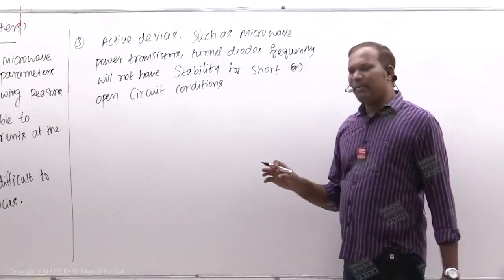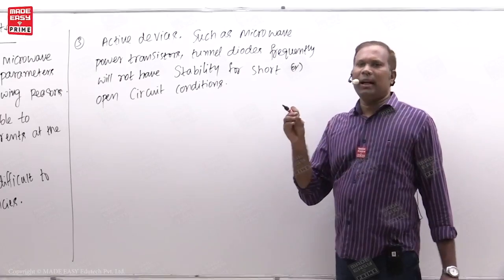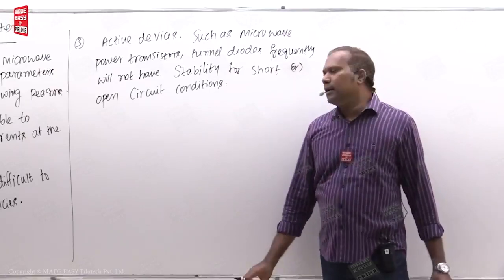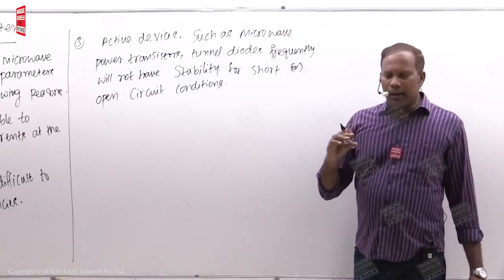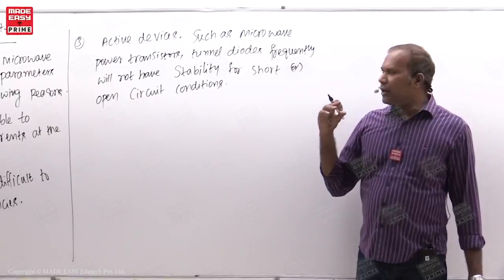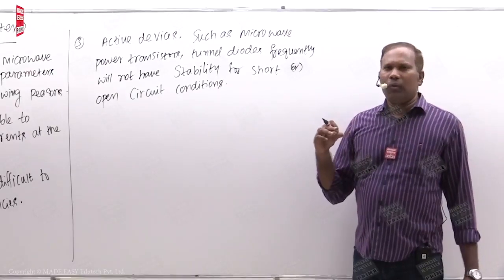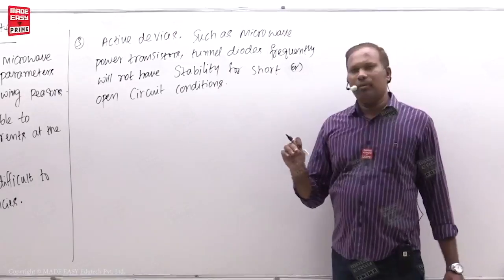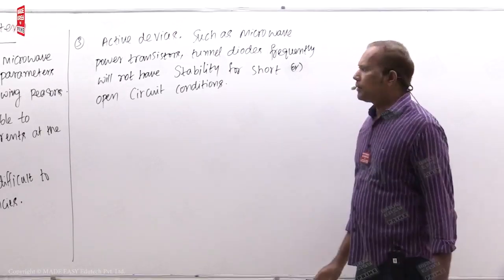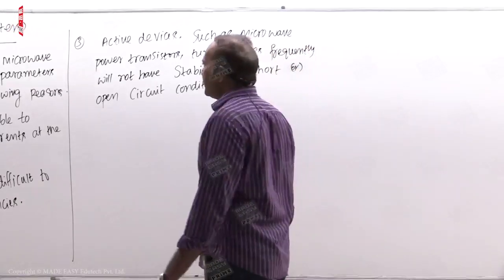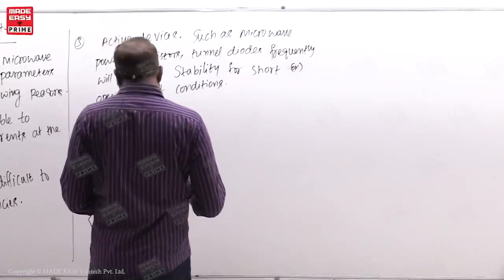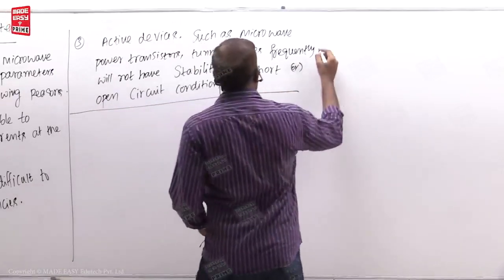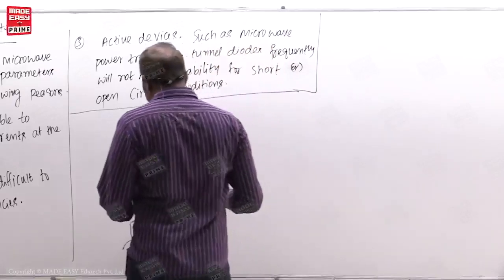Even though you use impedance matching, small reflections will be there. But even small reflections can easily disturb the tunnel diodes, Gunn diodes, etc. Because already at microwave frequencies those devices are very hot. We will be cooling them every time. But even if small reflections enter them, they easily go into the instability mode. So these are the reasons. That is why S parameters are used to represent the network: scattering parameters.